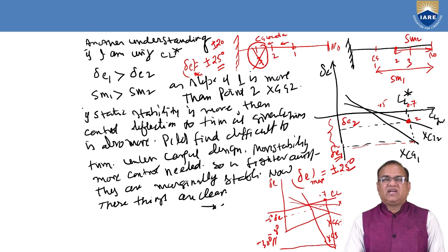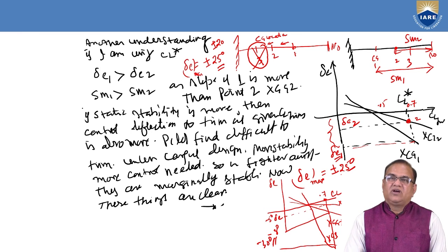These two equations are directly related with S, the area of the wing, and the area of the tail. Also the moment is related with the volume ratio of the tail, also tau and the coefficient of lift.